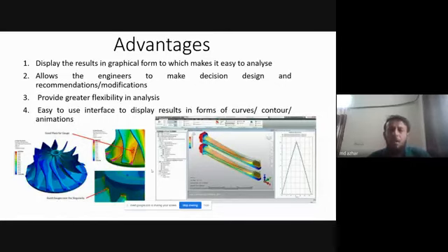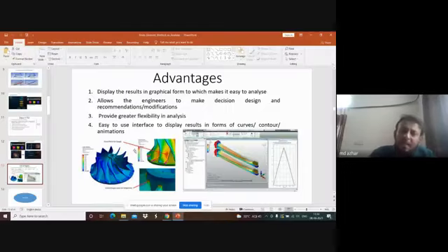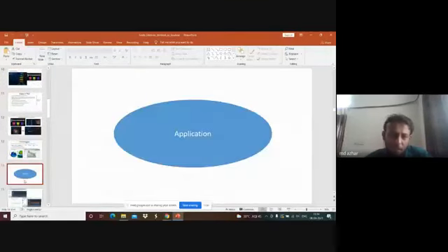So in this particular part, one can make some modification. What modification can one make? One can do a design modification, change the material, or do a selective laser heat treatment to increase the property here. So in many engineering applications, you have to know these things.